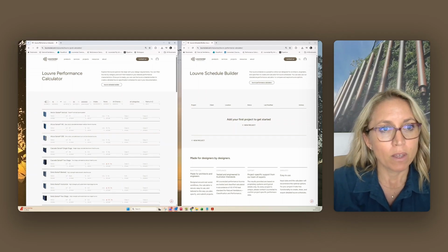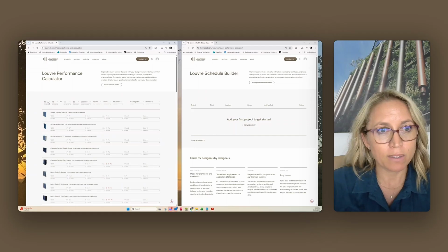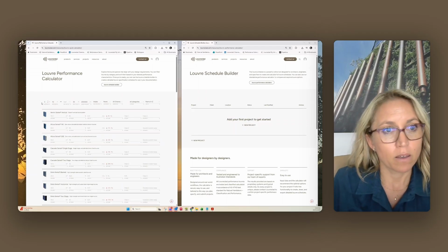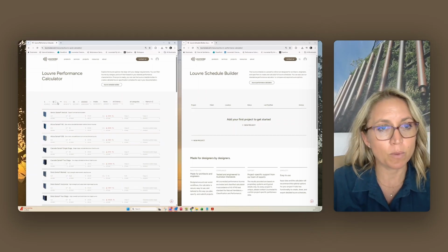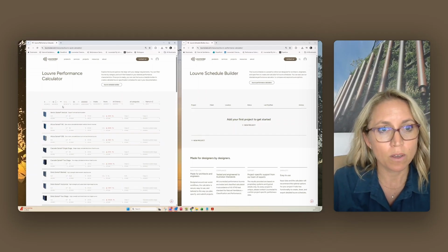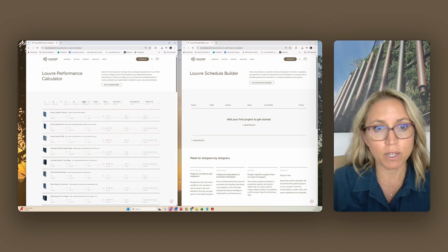As you can see, we've got a few fields here where you can enter the data on your louver. You'll have to enter the face width and face height in meters. That's the hard opening area for which your louver is going to be installed into. You can then enter your target pressure drop, say it's 30 pascals, and the flow rate you are working with for your project, or for this louvered area. You can then select intake or exhaust, and any accessories you might be working with for this particular louver. You can also select vertical or horizontal if that's critical to your project architecturally.